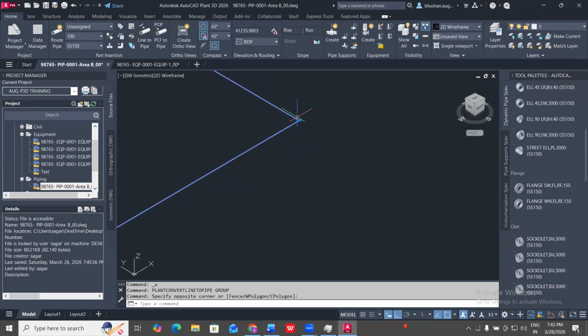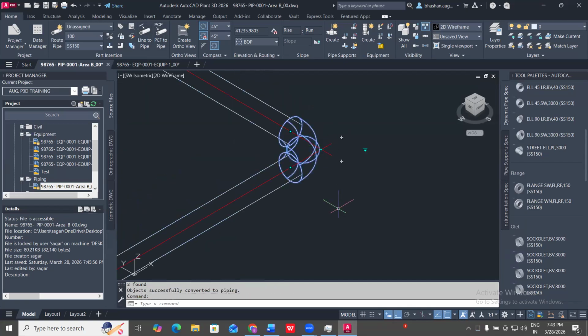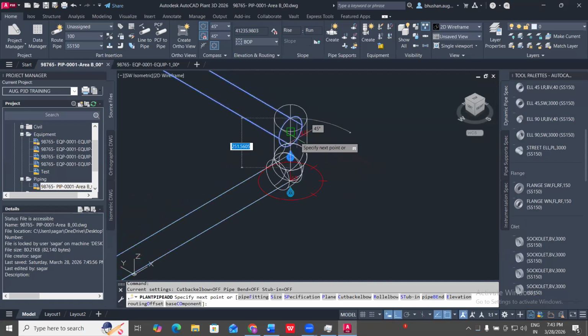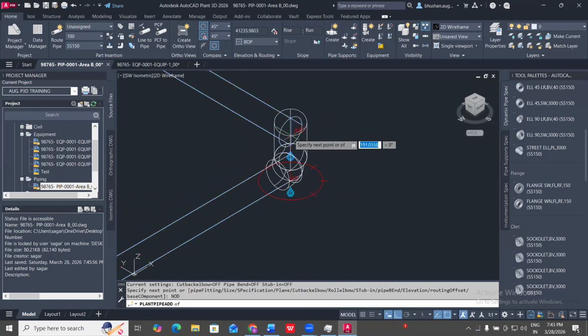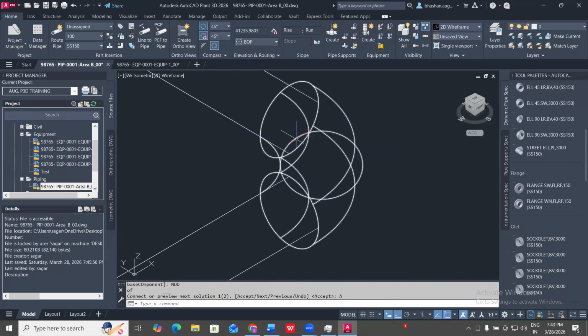If I deleted the elbow, can you delete that elbow? Okay, just a moment. I will click create line to pipe, and I click delete on this elbow. Now I want to re-add this elbow. So should I click the plus mark again? Yeah, you can click on the plus mark and select the node point of the pipe which you are connecting. It will automatically add the elbow there.